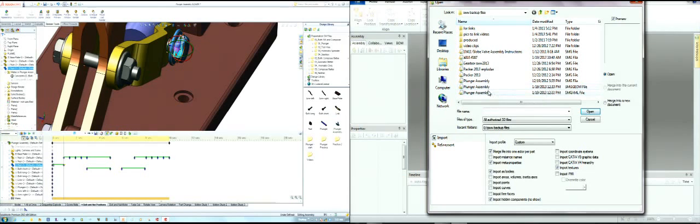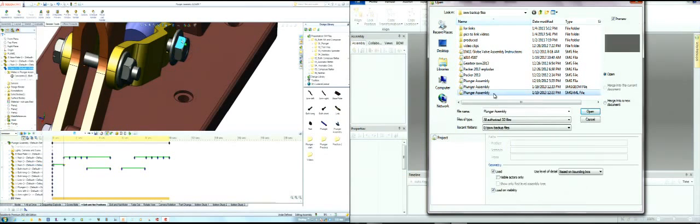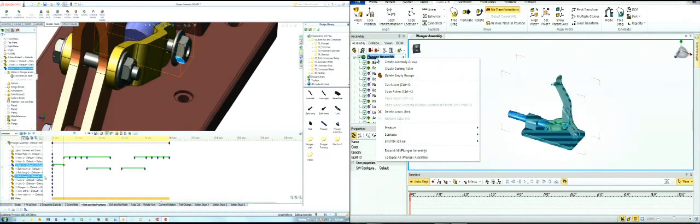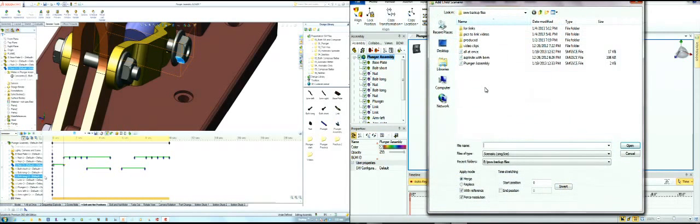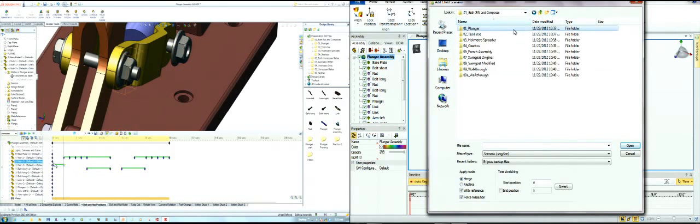Find the ring, the blue ring here, and rotate it, and that will capture both the linear movement and rotation movement. So this key point now says go from here to here and this at the same time. And I would repeat this operation over and over again, tediously.